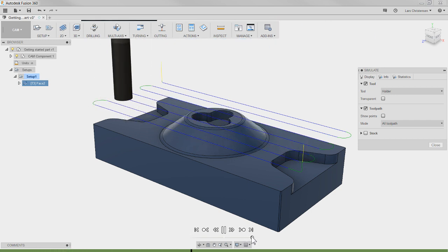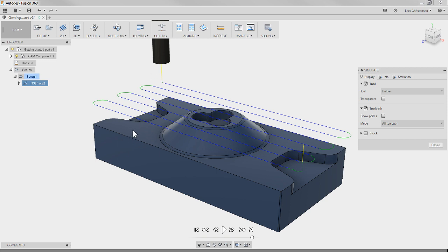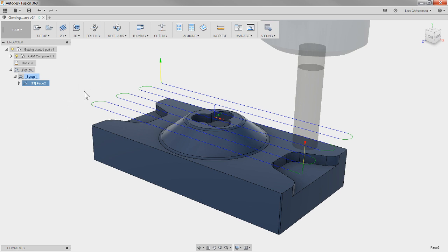One thing I like to throw in there quickly is that if you're using this end mill, and it's the same end mill you're using to finish the surface down here, using the same end mill for both makes it a little easier to get the height right, because you don't have two different tools that have been touched off. You're using the same tool, and it's really just the machine Z movement. All right, so this is the first operation I'm going to put in there, just a facing operation.